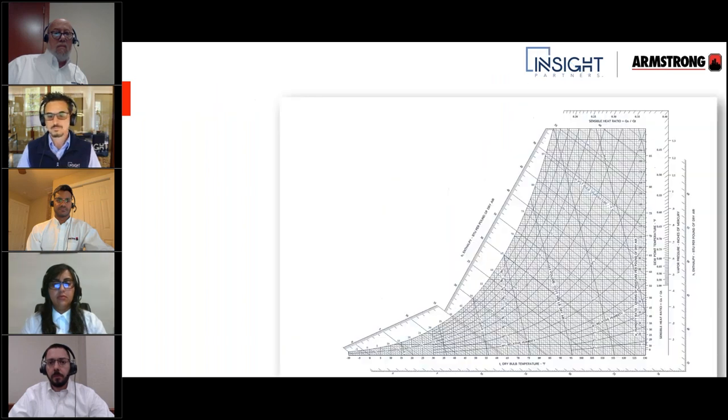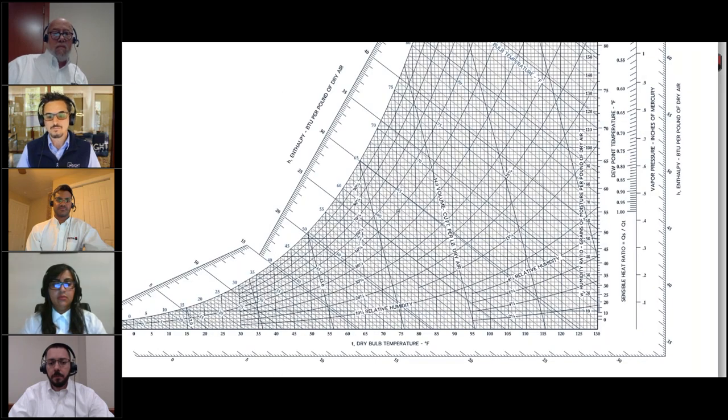So, okay, we're going to go through and plot different points on this chart. This is a good time, if you have it printed out, to play along with the chart. Okay, let's enlarge this and do some examples. Let's do some dry bulb points first. Let's find 95 on our chart and circle that, and I'll help you out here. So 95 dry bulb is right here.